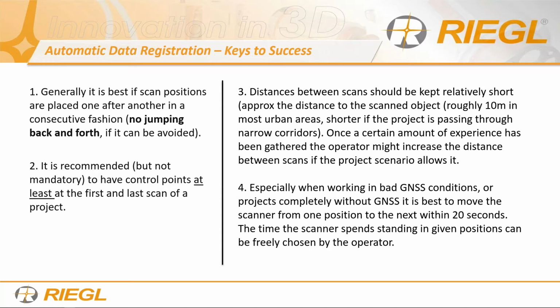But there's a best practice you want to follow for this, right? From one position to the next, you want to do it within 20 to 30 seconds. I know it says 20 here, but it's 20 to 30 seconds. Why? Because with an IMU, an inertial measurement unit, when you pause, what happens is that you drift, right? So the IMU needs to be moving the entire time in order to be effective. So when you pause, when you take too long to move to the next position, it just causes a drift, right? So you want to be able to move within 20 seconds.